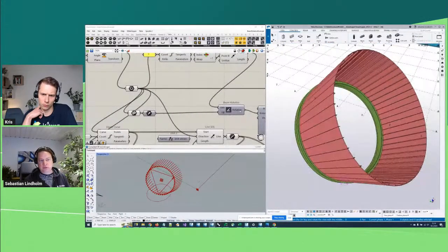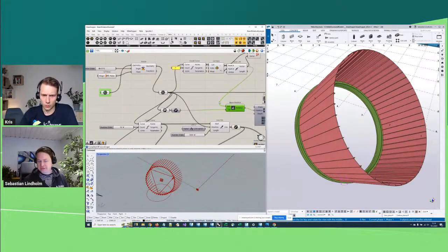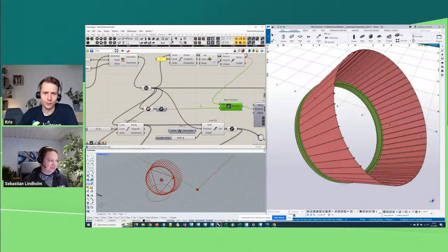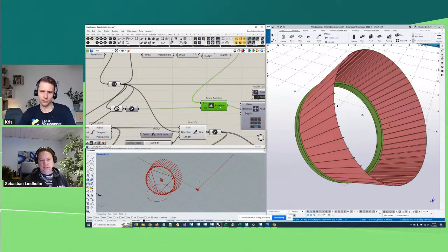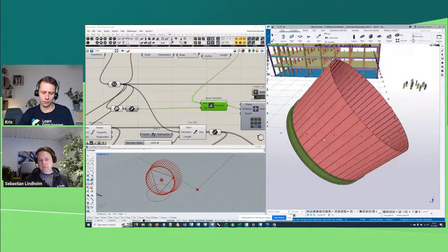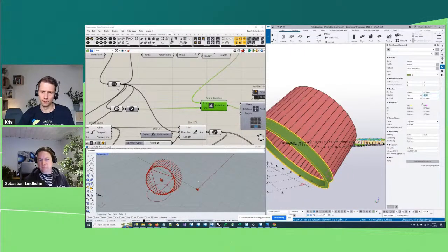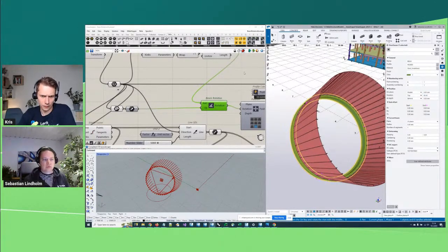So that can simplify. You can calculate the rotation angle. The output here is just an angle, a number. You can calculate it in Grasshopper if you know how Tekla works, but it's a lot of components, and I kept doing it over and over before just hard coding it into a component. So this component actually calculates the angle, right? Yeah, it calculates the angle that Tekla needs in order to rotate it correctly. So that angle then gets put here for the beams.